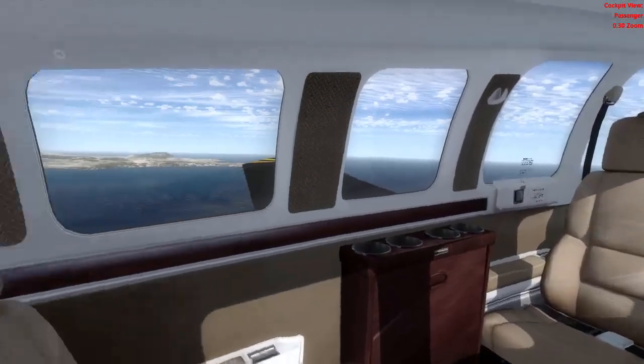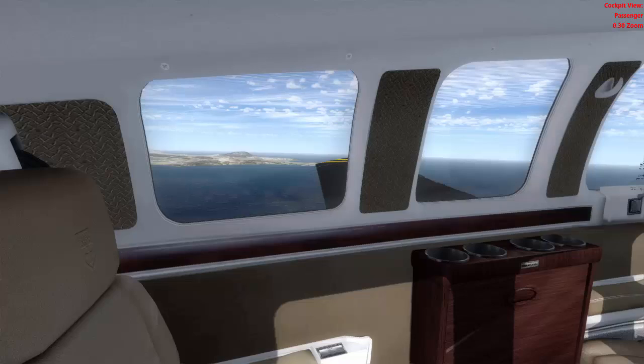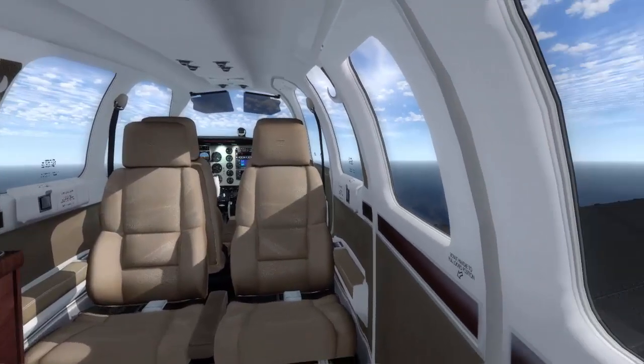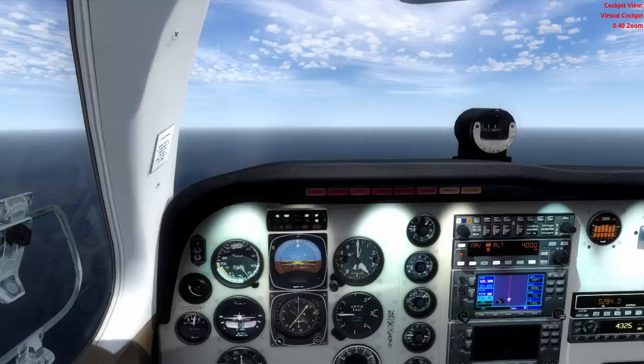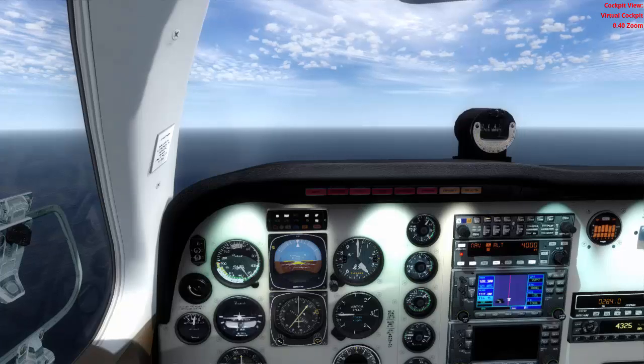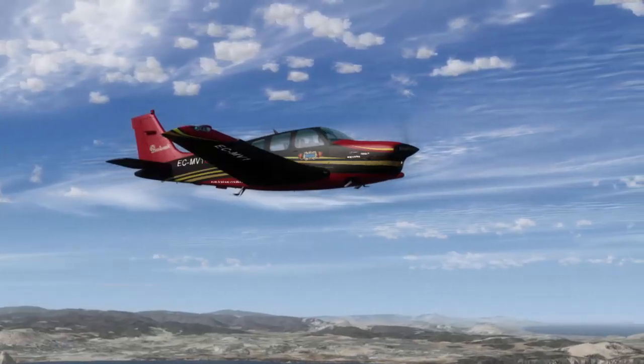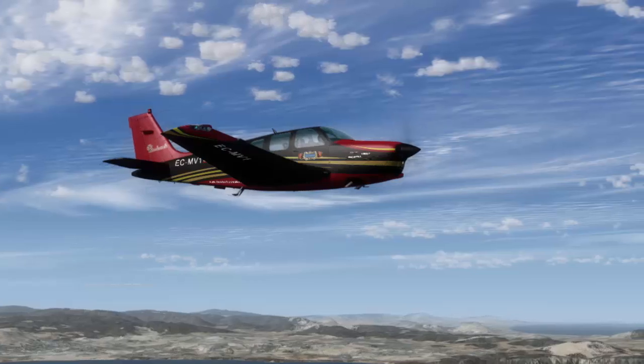No, I am talking in this case about the spy plane, okay? So just imagine you are very, very high. Even in that case, a descent rate won't work. The descent rate works only and only if you are at a certain altitude, at a certain point, and that point is exactly the point I told you before, the FAF, final approach fix, okay?